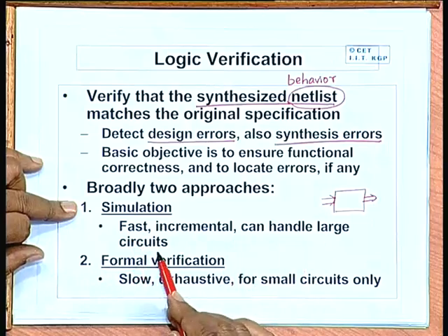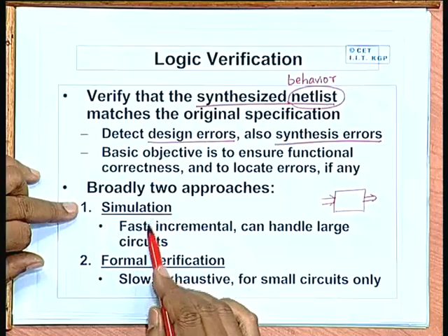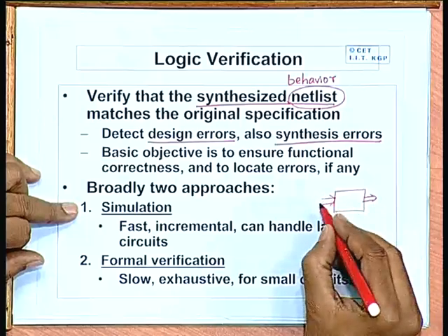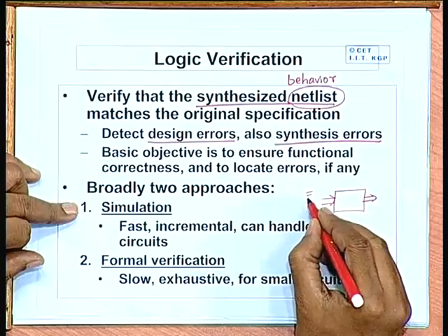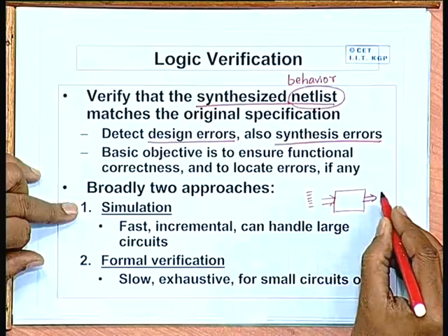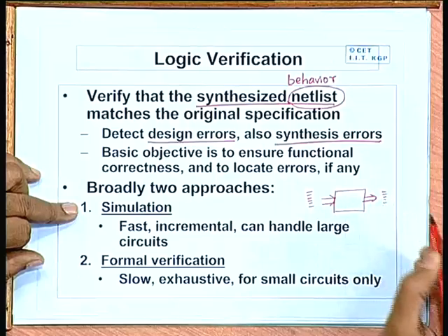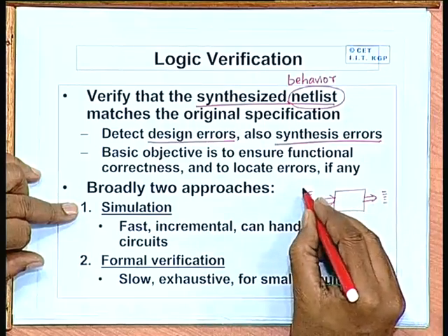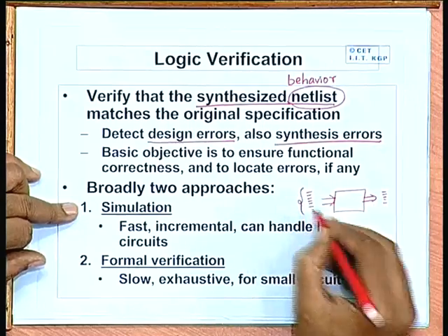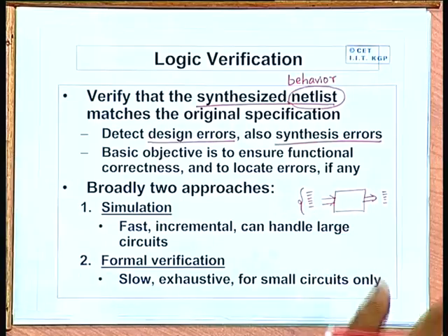It can handle very large circuits, but in simulation the only problem is that you have to clearly specify that these are the inputs I need to apply and I want to check the output for this. Now, the question arises of how many inputs you need to apply before you can say with confidence that I have verified my design. Naturally, it is a very difficult question, particularly if your design is complex, like a processor, say, if you are designing a CPU.